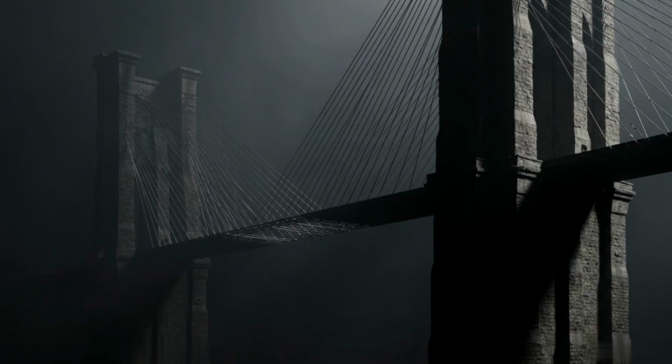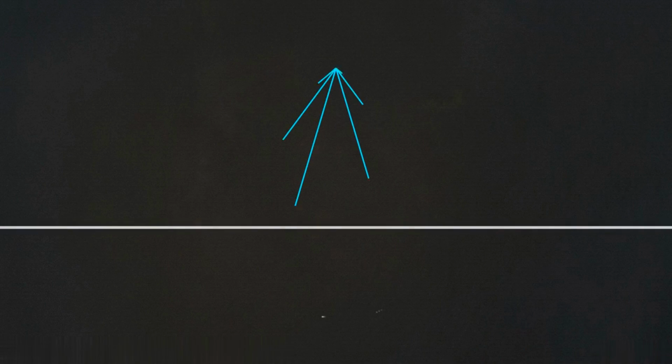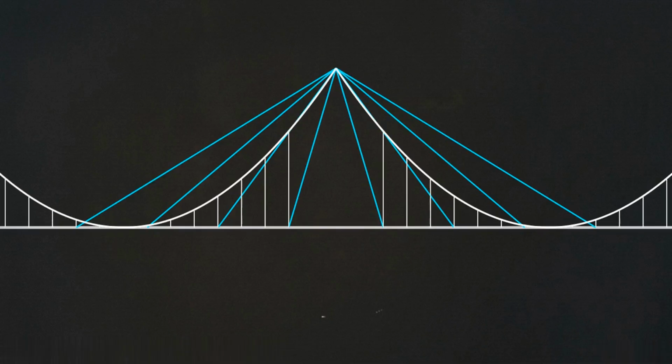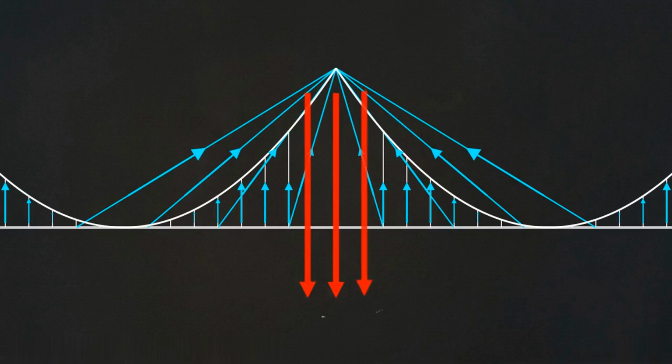The high casualty rate and the unknowns of early steel prompted an extreme defensive design approach on the Brooklyn Bridge. The Roeblings utilized a hybrid system. They installed diagonal stay cables radiating directly from the towers, running alongside a traditional vertical suspension cable system. Here, cyan arrows show vertical suspenders pulling the deck up in tension, while red arrows trace the load transferring into downward compression through the stone towers.